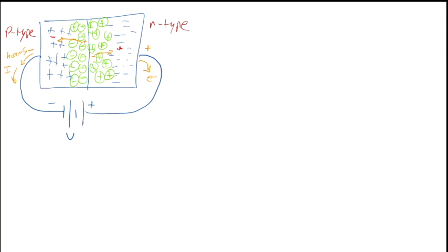And electrons are going to get kicked out on the N-type side, and they're going to stay majority carriers. But if a free hole wanders in over to this point, it's going to sense this huge negative voltage on the other side. The hole's got a positive charge, so it's going to get sucked across. And as soon as it gets sucked across the junction, it's now a majority carrier. Well, it's always a positive carrier, but now it's a majority carrier, and it will be rejected from the depletion region just like this one is. As soon as it crosses, it's kicked out.